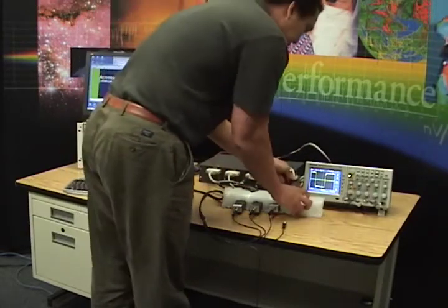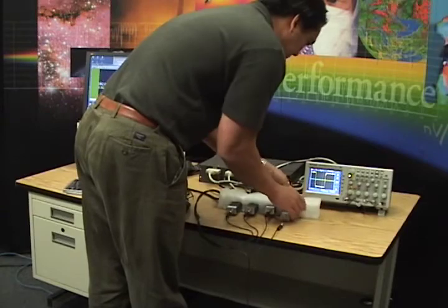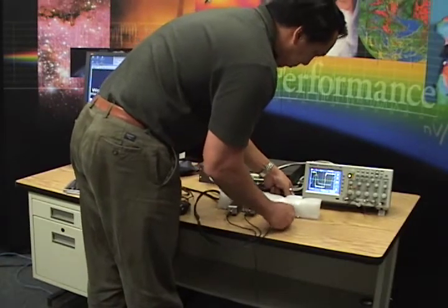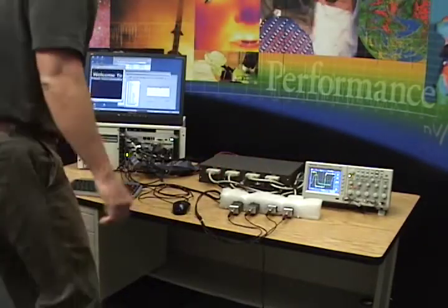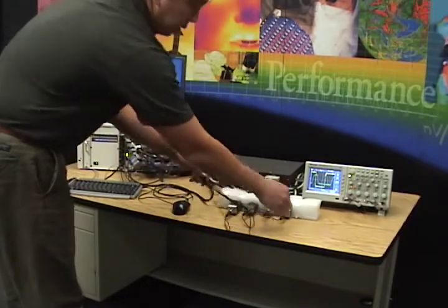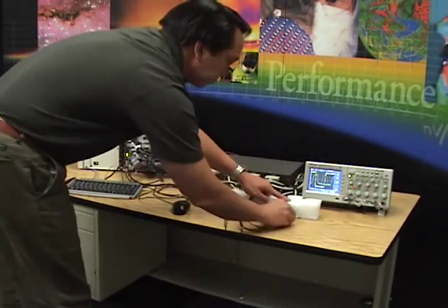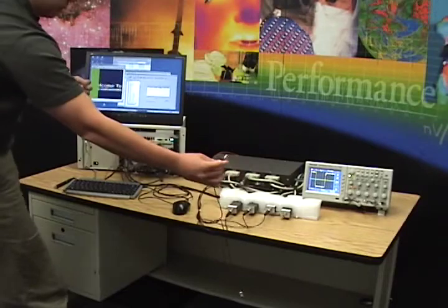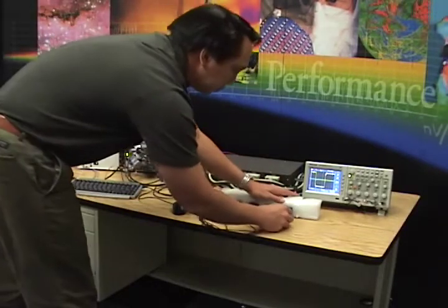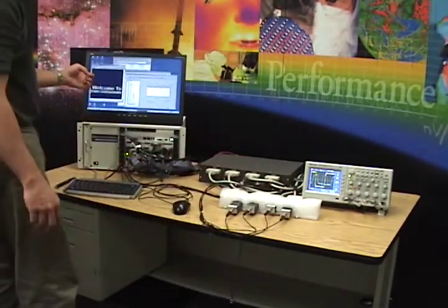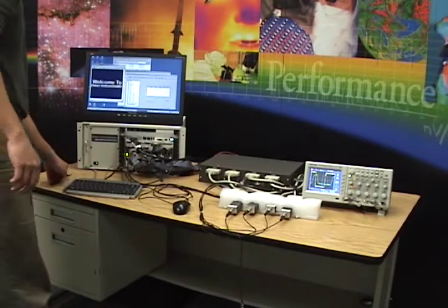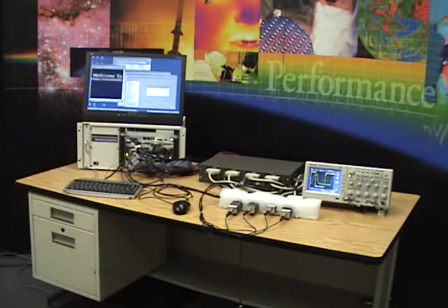For this demonstration, we will be digitizing a test pattern. These clock signals would ordinarily be driving your device. Instead, we are going to feed these into the preamplifiers and digitize our own signal. If I remove the input from preamplifier number 1, you can see the left quarter of the image go blank, and when I plug it back in, the image reappears. We are creating this moving image with our pattern generator and clock drivers and displaying it in real time.